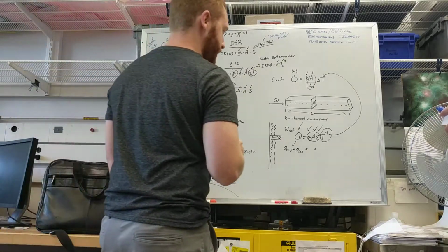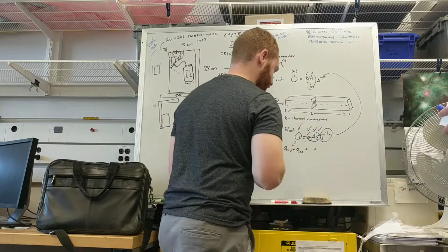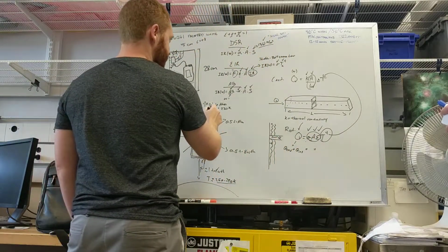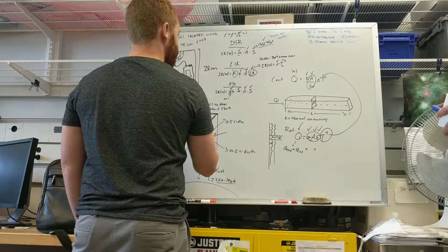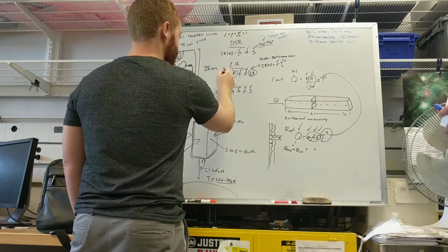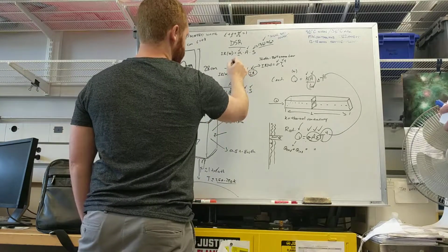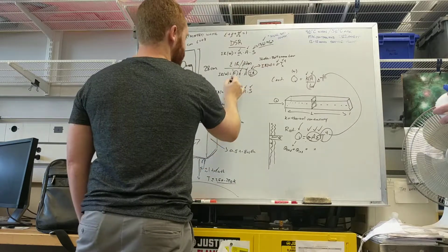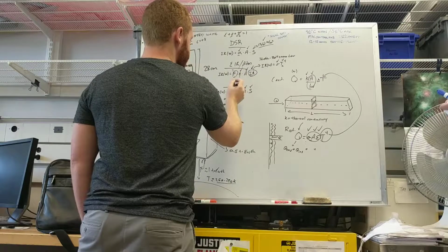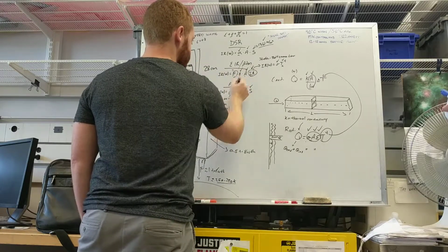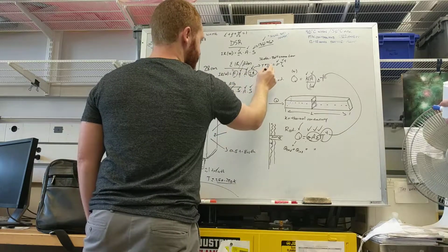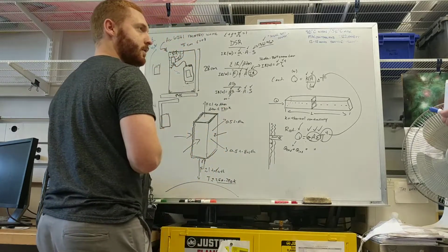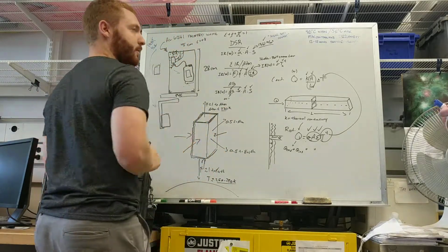Now, the reason for that is you do this analysis first. So for the top surface you would say, all right, well I know we're dealing with IR loading, we're dealing with this case. So this is Earth IR, but it also relates to the atmosphere. The U factor is 1, we know the emissivity of about 0.8, we know the surface area at the top, and we can compute this via sigma T to the 4th. And we know that T is 230 Kelvin for the air. So we know the Q environment now on that surface.